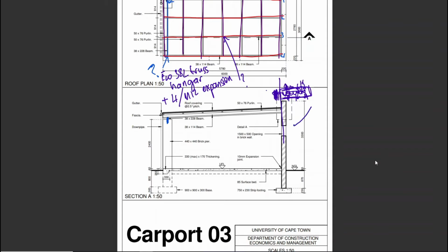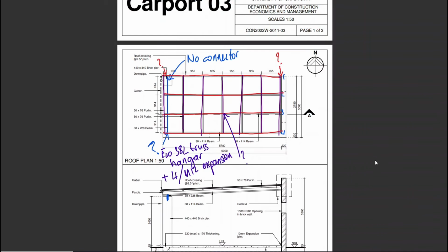And you keep tightening, and it keeps forcing and expanding. This expansion bolt is trying to push outwards and the brickwork is resisting it. And then you have quite a strong bond, quite a strong anchor. And a lot of these wall anchors work like this. There's a huge variety and they all employ a similar idea where you're expanding something and forcing outwards against brickwork. So that is the story with our main beam to brickwork.